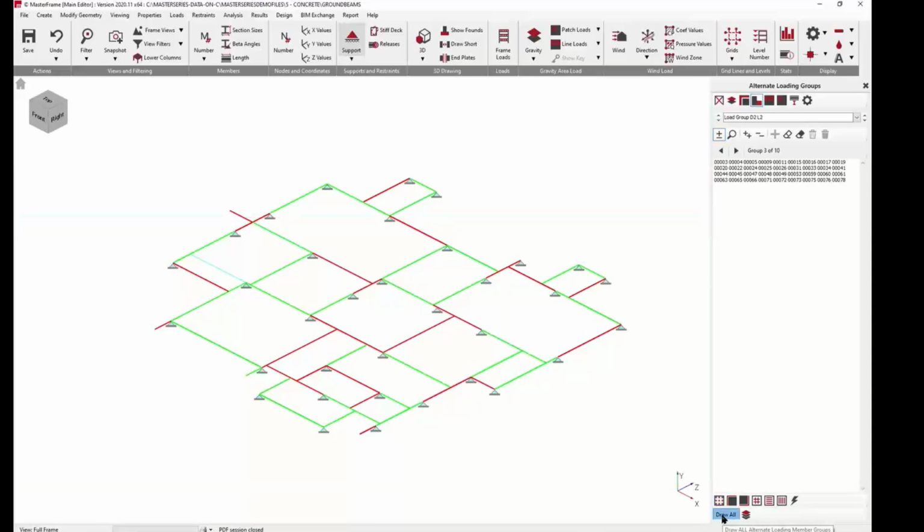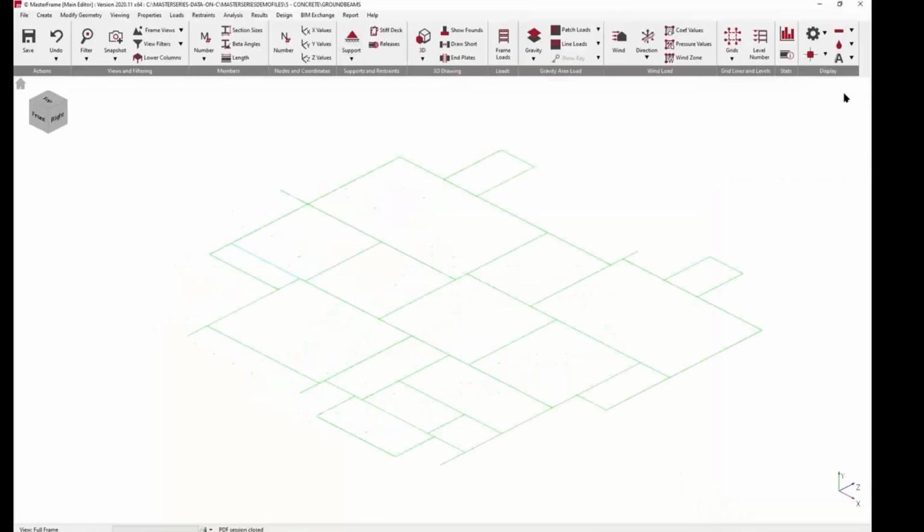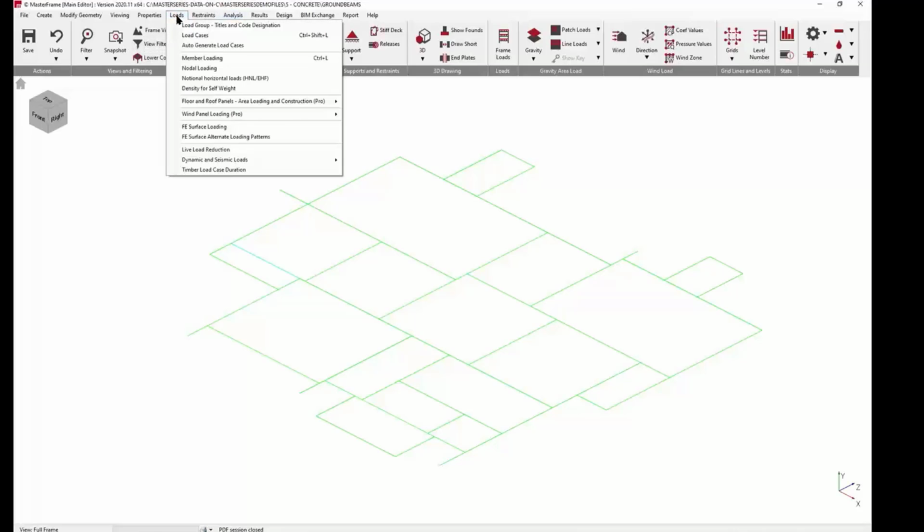And luckily we can draw both sets together and see all of them arranged out. That member doesn't exist, it's just a dummy member to allow us to span in that direction and then that direction for that portion. So everything is one-way spanning. That's all my loads done. Now moving forward quickly.